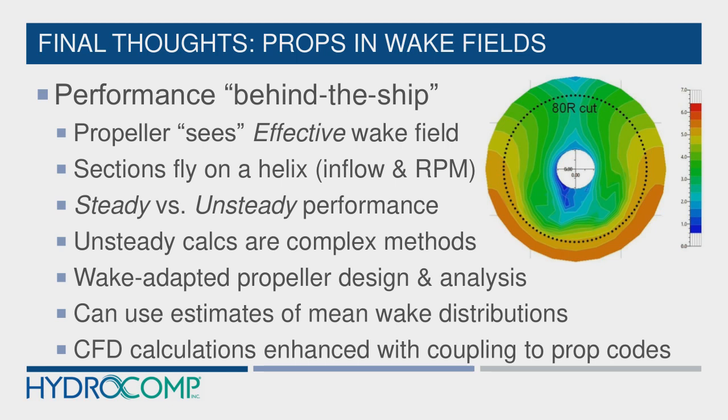And there's a number of different approaches that have been used in the literature. You'll find technical papers on how those methodologies are done. That's not something you can really do with a fully interactive CFD calculation, because a nominal calculation, a nominal wake field, is without the propeller. You can only do that at one velocity, take a snapshot. And so, that's where you would either do that in model testing, do that in CFD, and then try and figure out what the equivalent effective is for that.